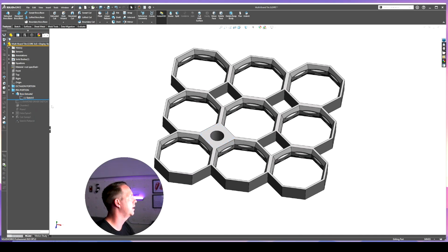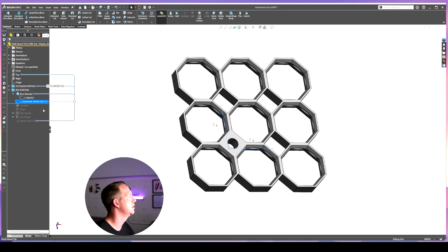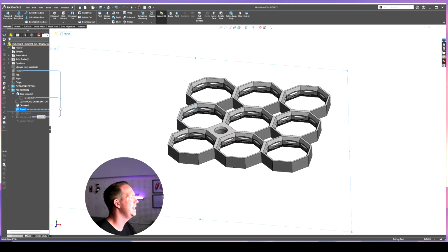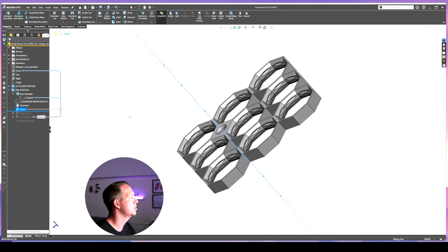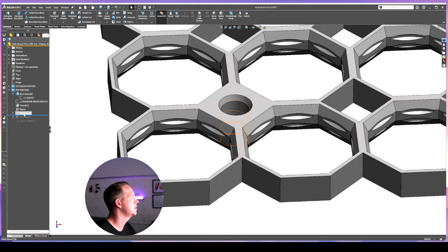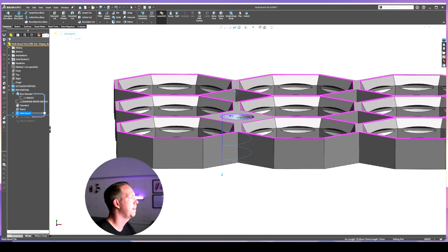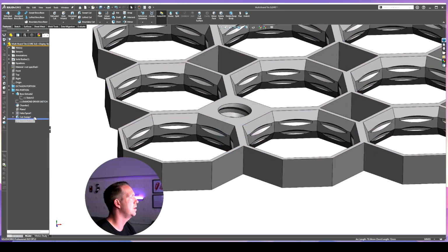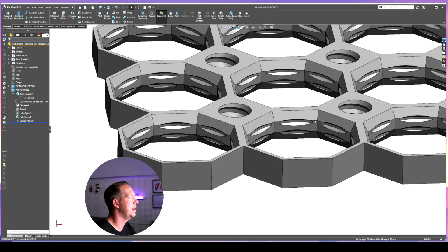Okay. Again, pretty straightforward. Then we put in our sketch that's driving these diamonds. All right. In this version, it's 3x3, but in others, those numbers change. I then put my chamfers on the hole. I've created a plane here because I need to get the sketch exactly in the center of where that hole is. I've got a helix, which you can see here, and a cut sweep, which creates that thread, and then a sketch pattern.